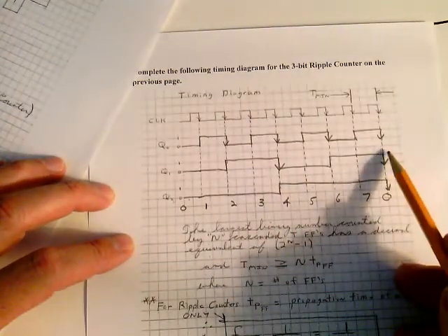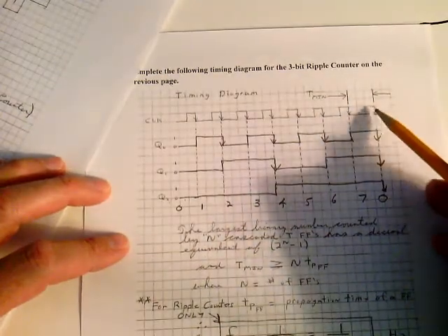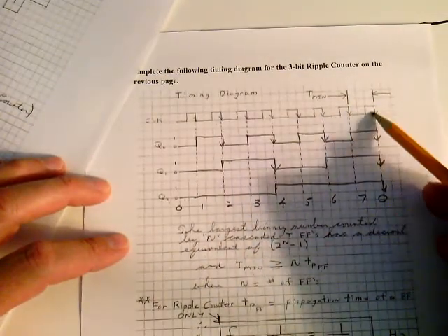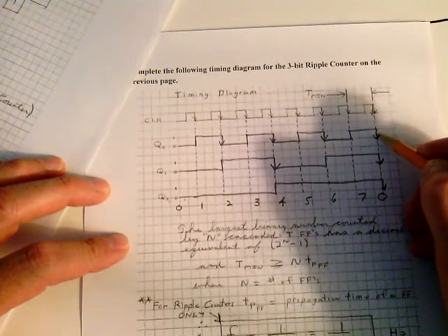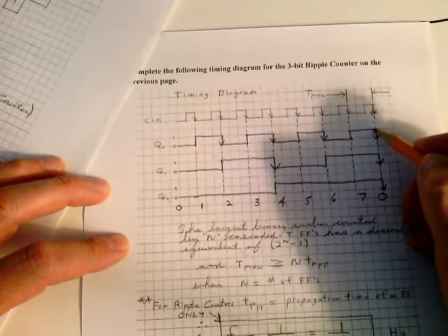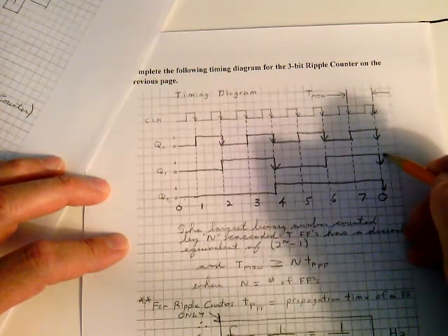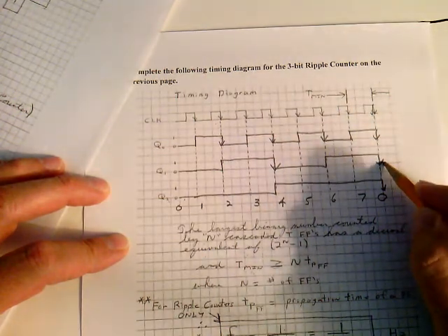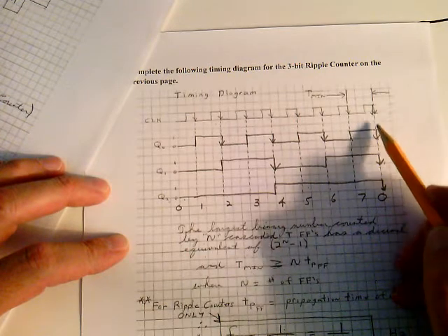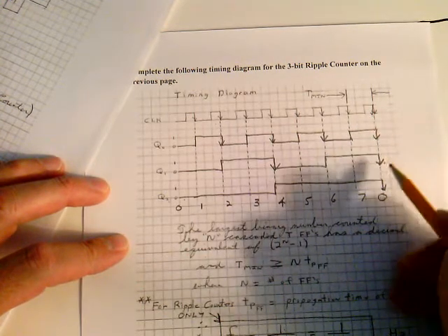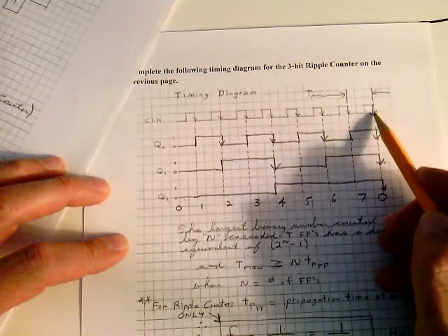Well, if you look up here, it's pretty easy to understand. You cannot make this period any smaller than what it takes. This clock goes low. You have some time to make this. It takes a while through the first flip-flop for this to go low, and then for the rippling through to the next flip-flop, this is going to go low sometime later. Then this goes low sometime later. The delays of these flip-flops here and here and here, they're stretching out into the period up here.